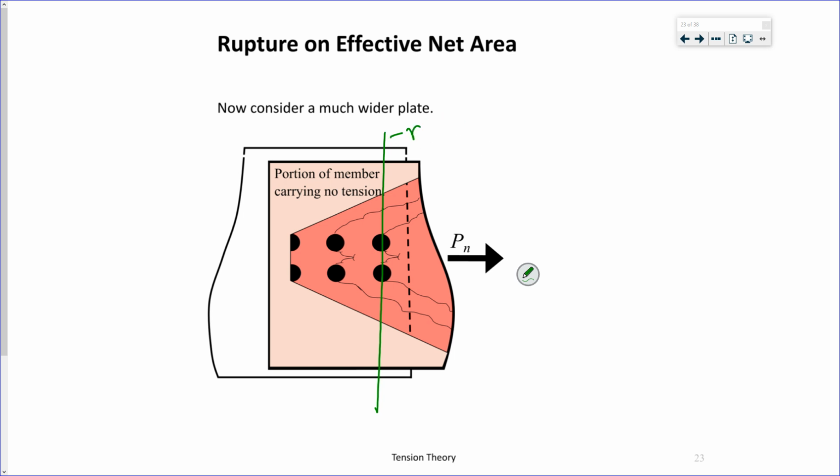But due to the flowing of forces between transferring the force from the plate to the bolts, right, along this line and along this line, by the time I get to my rupture plane, not all of the member is actually participating.